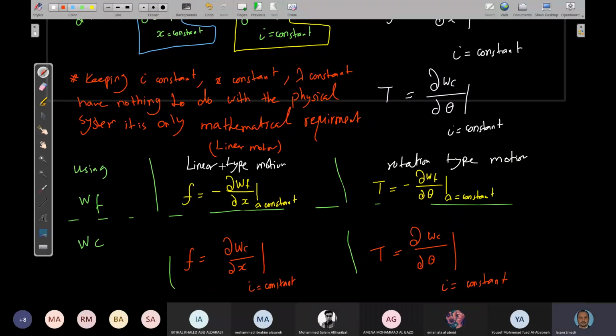Because if I do not neglect the saturation or the eddy current, in the end of the day, all of you know the BH curve or the I-lambda curve, in general, we plot it like this. And simply here we say that the core entered saturation. In general, if we need to design the machine, we design it near the knee here in order to optimize the torque. So in actual life, the magnetic circuit is nonlinear, even for a linear motion or linear motor.